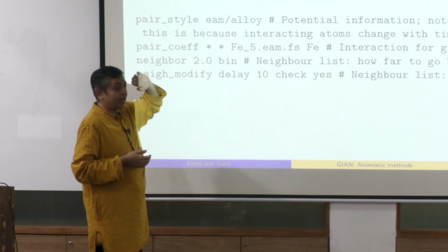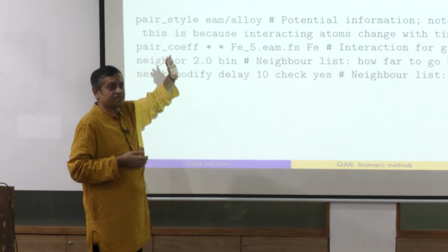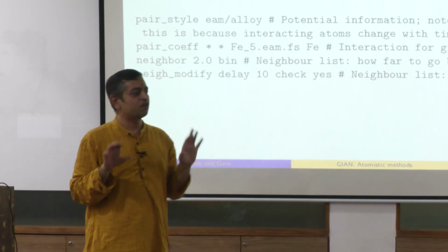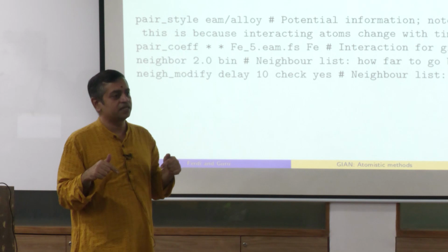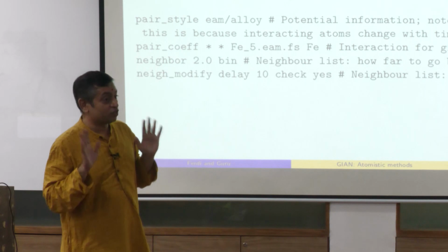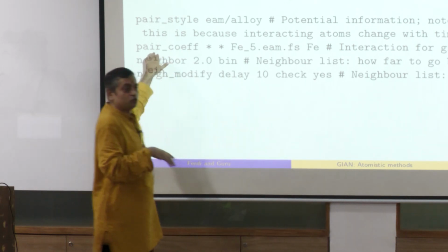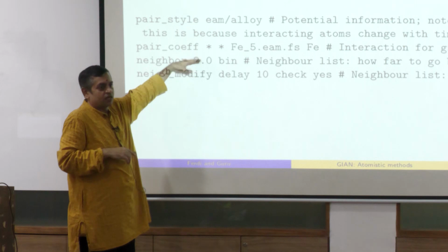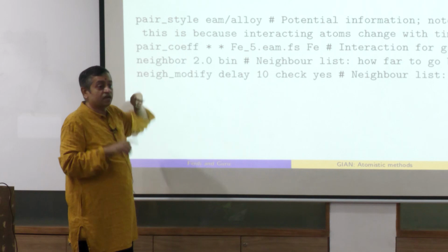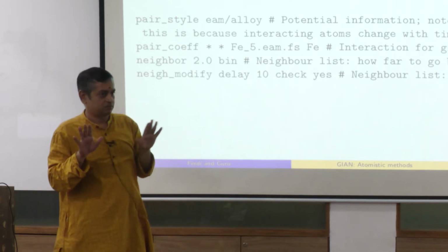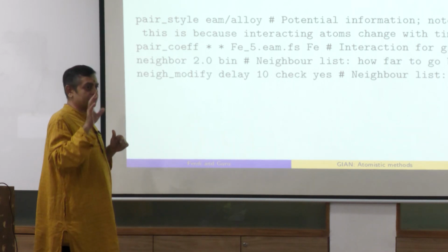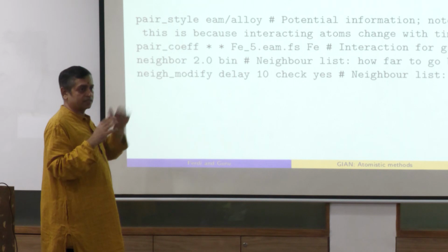For example, you can have a wild card LJ where you define some parameters for all the interactions, and then in the next line you say for 4 and 5 this is the interaction, and for 4 and 5 it will be overwritten. You have to remember that. It does not matter that you said something in the 5th line; whatever is the latest one you say is the one LAMMPS will consider for that particular pair. Again, this is in the manual: the latest overrides the previous commands.